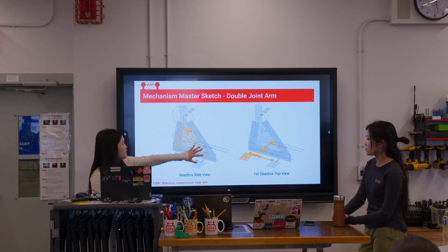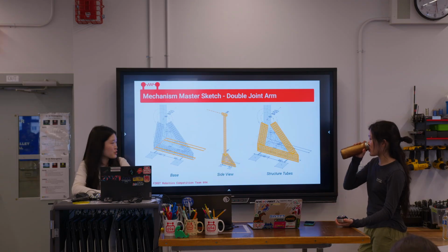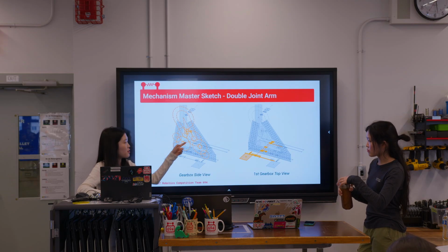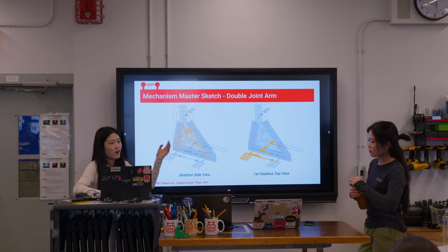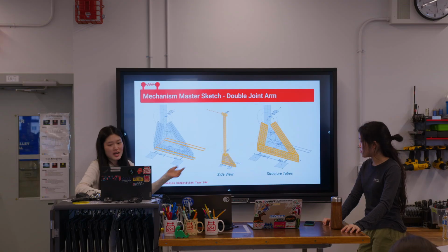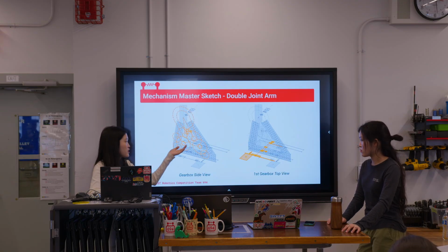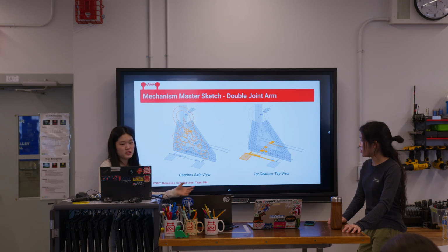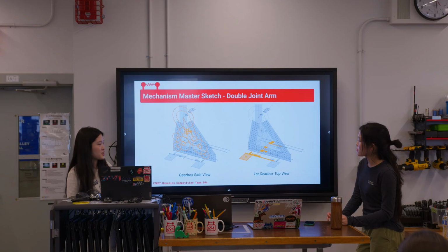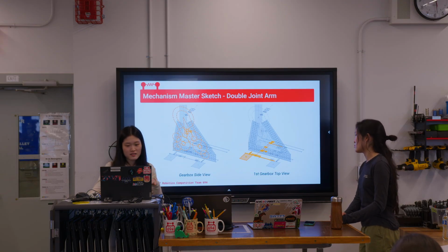All of them are in relation, and the reason why I made the structure first before adding the gearbox is because the shaft going through these gearboxes and the bearings that are going to be on the side should not be touching the structure. That is why it's important to have the structure tubing first before you add on the gearbox, because the gearbox is not supposed to touch parts on the structure, which is why the order in which you sketch things is important.